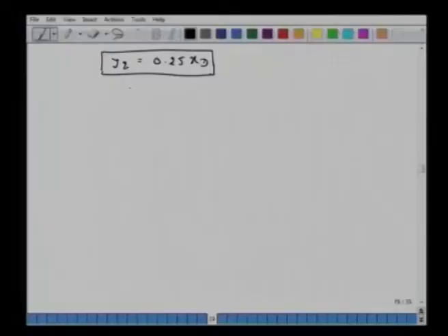Alright, so here we are trying to solve analytically. Why? Because we cannot solve graphically, as the compositions are not known to us. Alright, so let's continue with this. Now, starting from x_T, which is the same as y1 because it's a total condenser, we have connected this to y2.